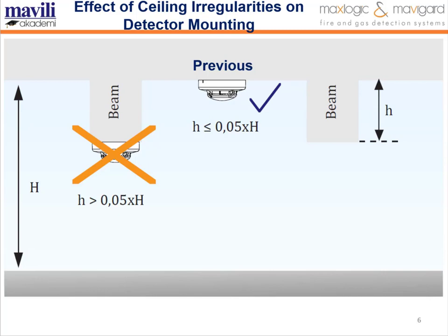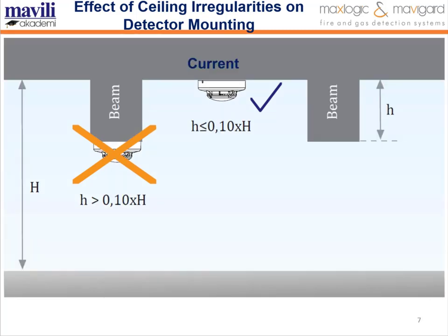In ceilings with beams, if the beam height is less than 5% of the ceiling height, the ceiling should be considered flat and radius limits applied. 6.5.1 General regulation is about ceiling irregularities which are less than 10 mm. Irregular ceilings with a depth of less than 10% of the ceiling height should be treated as if they were flat and radius limits of 6.5.2 should be applied.